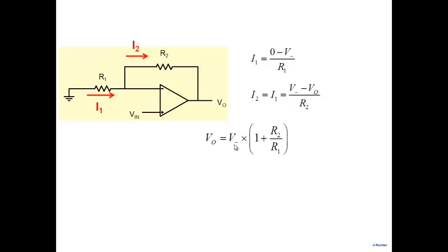How do I write V minus? Well, we know the general op-amp. The output voltage V0 is equal to the open loop gain of the op-amp multiplied by the net voltage at the terminals of the op-amp, which is V in minus the voltage at the inverting terminal. Correct? This is where we are heading. If we take AOL, the open loop gain, which is very, very large, what you will find is that the voltage here is the same as the voltage here, right? That's where we are headed here.